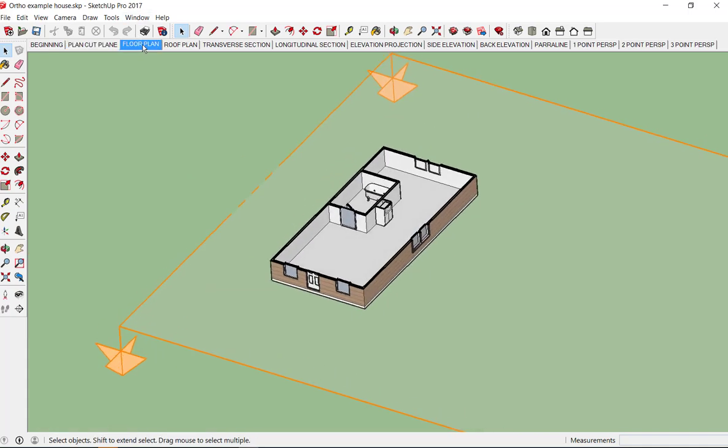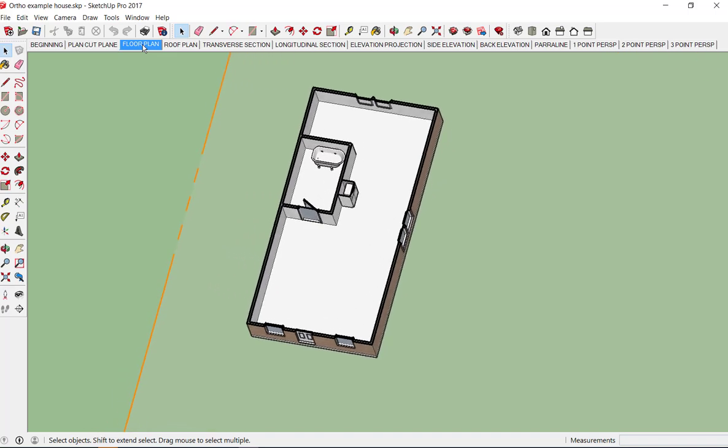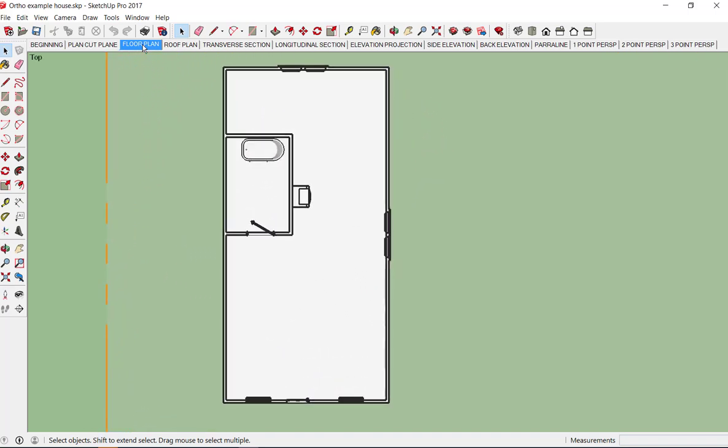So let's show you how a floor plan actually looks. We typically draw our floor plan square to the world at a 90-degree angle, and the door swings are drawn graphically, sometimes at 45 degrees, most of the time at 90 degrees open. The windows might be drawn simpler, just graphically. When you cut through a tall cabinet, like I've got in my little example, you probably wouldn't show the drawers and everything. That's just because I'm using SketchUp for an example. In an architectural drawing, this would just be a simple box. But that's our floor plan view.